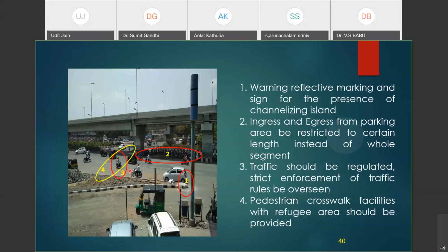An enforcement issue, you can see in point number 3, there is contra flow. Vehicles are moving in the opposite direction. Again, I say, we try to make it an enforcement issue and blame the vehicles that are moving in the opposite direction, but we need to understand why this motorist is moving in the opposite direction. The person is moving in the opposite direction because there is some origin destination pair which the designer has missed. There is a location where this motorist wants to go, and the path given to him by the designer is a much longer path which he has refused to accept, and chose to break the law and take the shortest path to reach the point where he wishes to go.